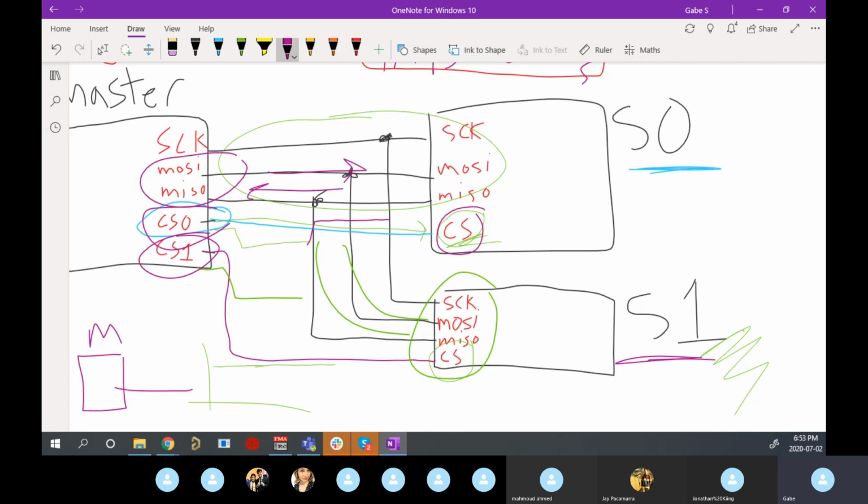All we had was one SDA line and a clock line. And this SDA line went to everybody, all the slaves in the neighborhood. I guess the clock too as well. And the way we talked to different slaves was by giving them an address, right? Each one had its own unique address. And I would talk to the second one by sending the second one's address, right?